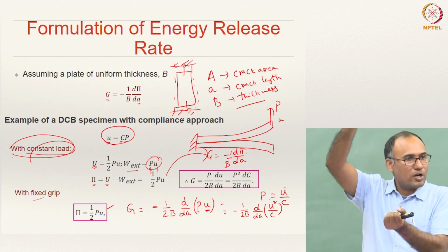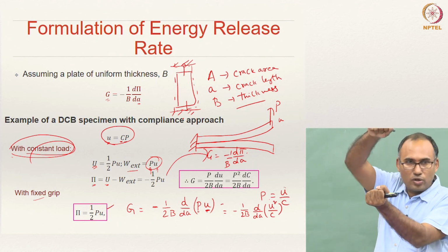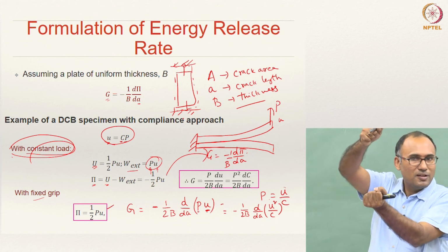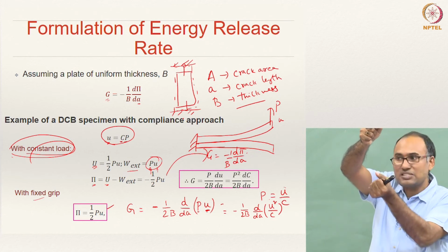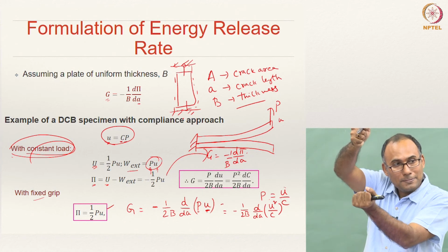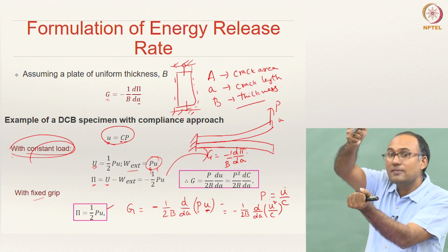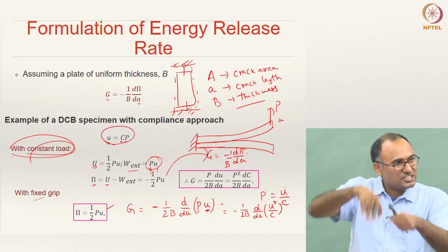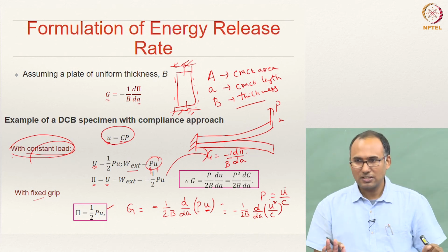In the previous case, what happens? You are applying a constant force, you have applied some force, you got some displacement, and you are maintaining the force same. When you are maintaining the same force and the crack is propagating, what will happen to displacement? Increases or decreases? Increases, because for the same force, the stiffness of the component is decreasing as you are increasing the crack length. Alright? Clear?